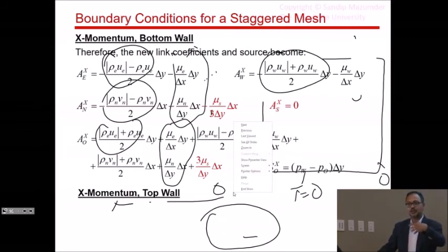So what does that mean? Second iteration, your velocity has now become non-zero because you've already solved the momentum equation once and I already drew the contour profiles, right? So your velocities are no longer 0, which means second iteration, these advective links will get activated. And if you have a bug in one of those, your code will blow up. So the first iteration gives you a sanity check of just the diffusion terms. Second iteration, once it works, then you can be almost sure that your momentum solver is working.